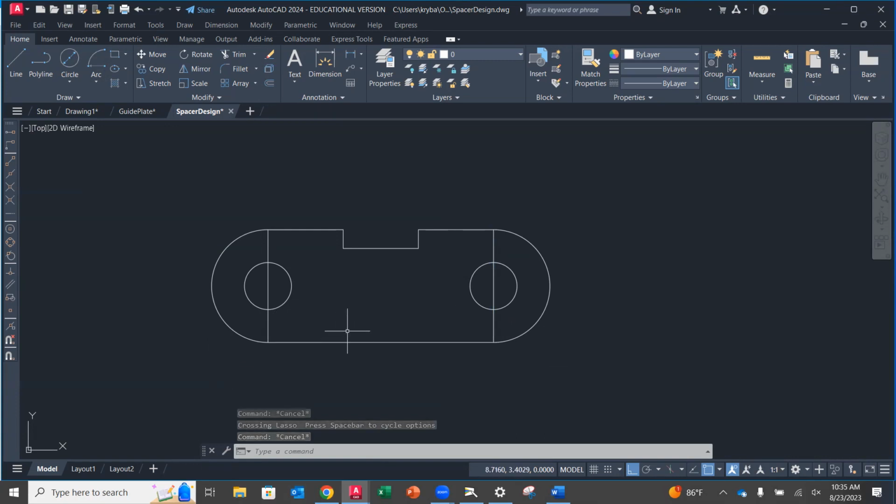But remember AutoCAD standard: you'll notice that it does get around it sometimes, but you'll also wonder how come it's not working? The best way to approach any command in AutoCAD is to tell AutoCAD what you want it to do first, rather than on the back end telling it after you select something. It's the better way, especially when you're learning. So the selecting isn't bad, but let's tell it we want to erase first. That's the only difference. I'm going to go up to my little eraser and say, AutoCAD, I want to erase.